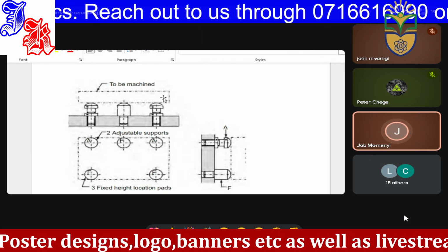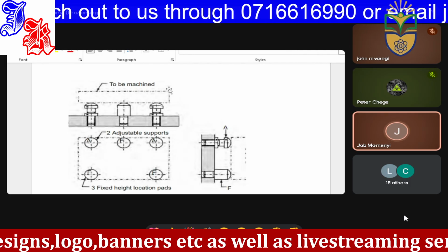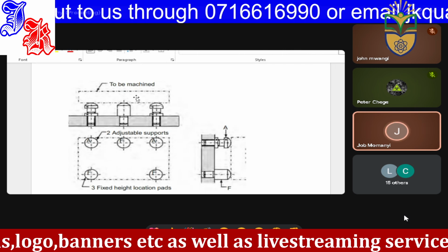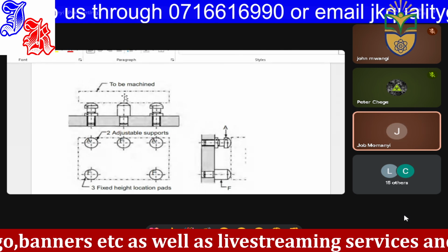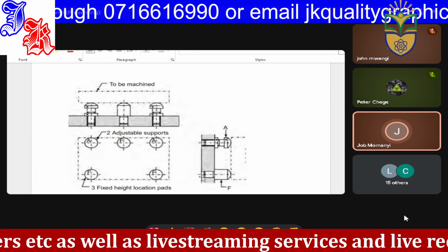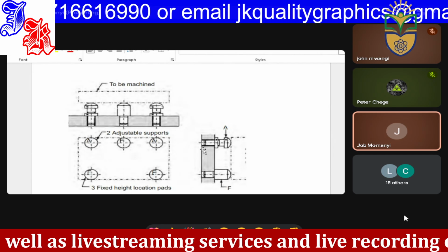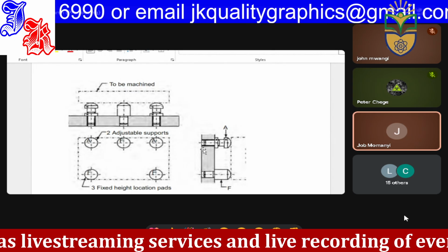For example, while the milling cutter is moving towards the left, this workpiece cannot move towards the left, because we have this barrier here. We have this barrier AF here, so it cannot move towards the right.